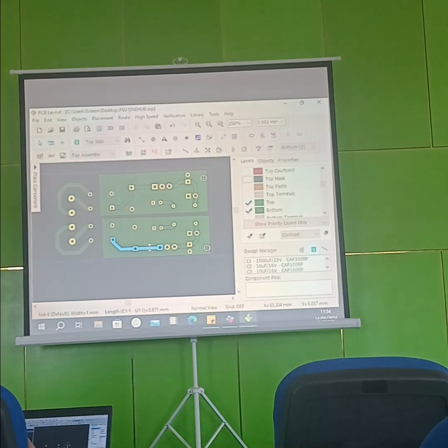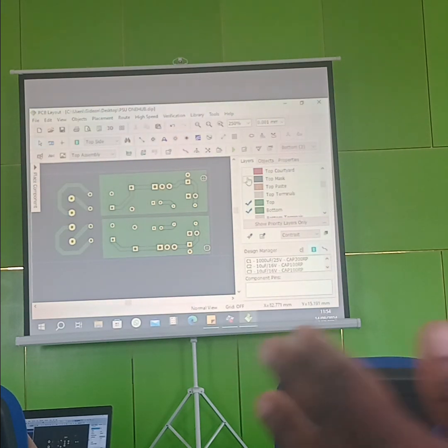Yes. So assuming you have a board and you want this trace to be exposed from this point to this point, you have to make it top mask. Then where do we normally use top mask? We use it in case you have a trace whereby higher currents will flow through that trace, for example an inverter circuit board.